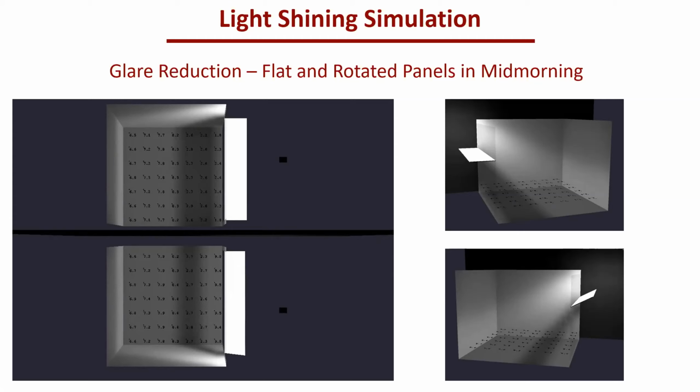What are these things right there? So all of these are the calculation points. In this one, they're spaced 3 feet apart, and they're just giving a foot candle calculation at that point.